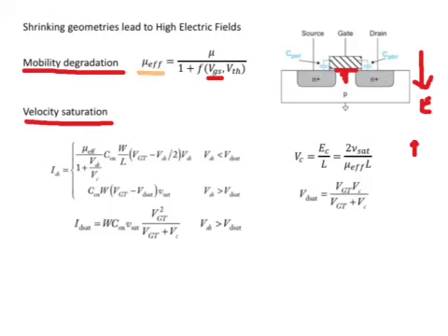This is modeled by a corresponding reduction in the mobility. Basically, we now have an effective mobility that is correspondingly reduced and depends on the magnitude of the gate to source voltage. So if you have a higher VGS, the mobility degradation is greater. Typically, this function f is some polynomial relationship with VGS and VTH, with some non-integer factor. There are several slightly different models, but the important point here is that mobility degradation can be represented by a reduced effective mobility.